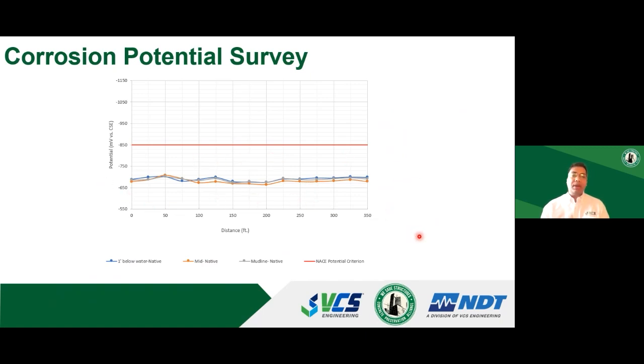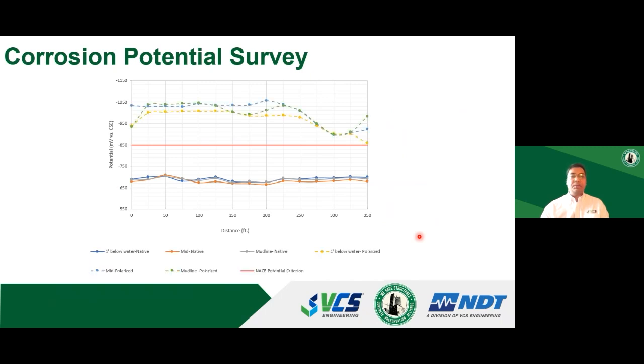Now, when you implement corrosion mitigation options for, let's say, bulkhead walls, sheet pile walls or combi walls, you tend to install something called a cathodic protection system or galvanic cathodic protection system. Those are the bulk anodes, like zinc or aluminum bulk anodes welded onto the steel that will protect the steel from corrosion. Once you install the cathodic protection system and you take the potential measurements, you see there is a sudden swing in potential.